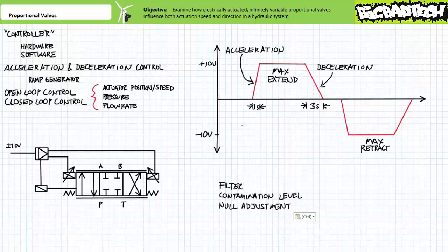Moving on. Proportional valves are fussy, picky, finicky, persnickety beasts, as fragile as an origami butterfly made out of a $1,000 bill, and must be treated as such. Good filtration and proper fluid selection is essential to the proper operation and reliability of a proportional valve, and as such, systems incorporating proportional valves often necessitate stringent contamination levels and inline or pressure filters upstream of the proportional valve to protect their fragile inner workings. Additionally, some proportional valves go to the trouble of including small built-in filters. Failure to properly filter fluid or using cheaper, i.e. dirtier fluid will result in progressive loss of functionality.